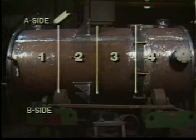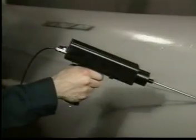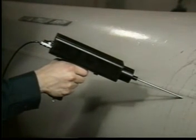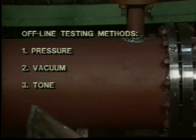Check 4 test locations on one side, then 4 locations on the other side. This method is effective for ongoing monitoring of gross tube leakage. Small leaks in peripheral tubes or gross leakage in central tubes can be detected. In an offline environment, 3 methods for testing tubes are used: the pressure, vacuum, and tone methods.